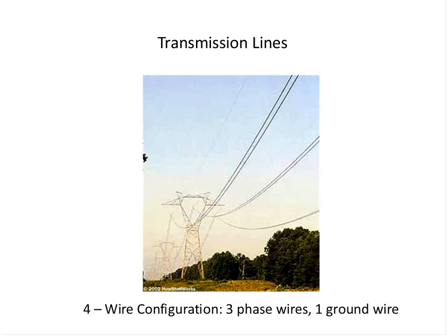And sometimes you'll have multiple wires, as in this case, so you may have 2 sources that are carrying electricity, because it's very hard to get right-of-way in transmission lines. So once they get a corridor, they try to carry as much electricity as possible. And as I'll get into later, AC currents are a little fickle. They have skin effects and things like that, so there is less than optimal transmission of electricity. And that's when I'll show you the benefits of high voltage direct current also, and how it can overcome things like the skin effect.